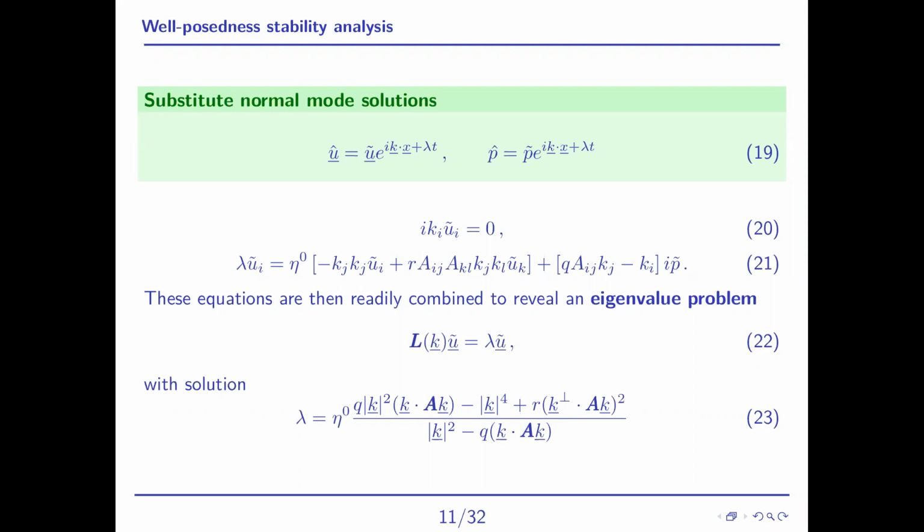So what we did is actually solve equation 21 for the pressure, provided that we know equation 20. We're reducing the number of unknowns by solving for the pressure perturbation, just by the fact that equation 20 is the dot product of the wave vector with the velocity.